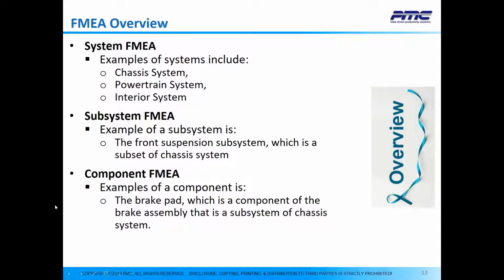Finally, the component FMEA, which is a subset of a subsystem FMEA. A good example of that would be the brake pad, which is a component of the brake assembly, which is a subsystem of the chassis system.